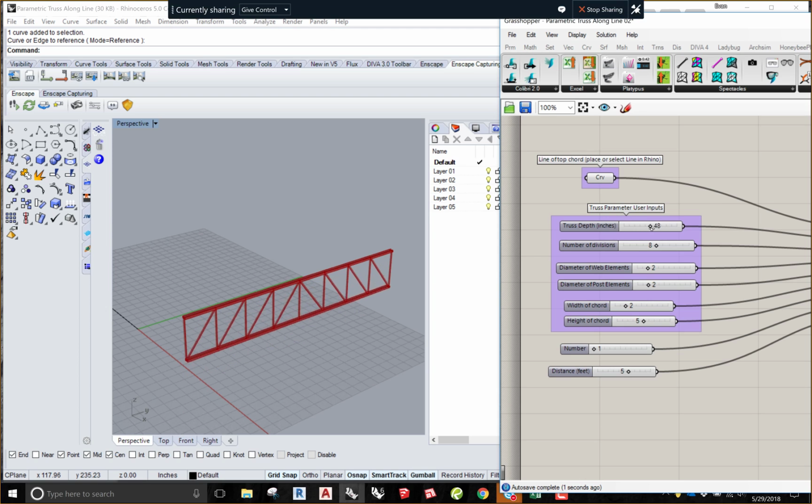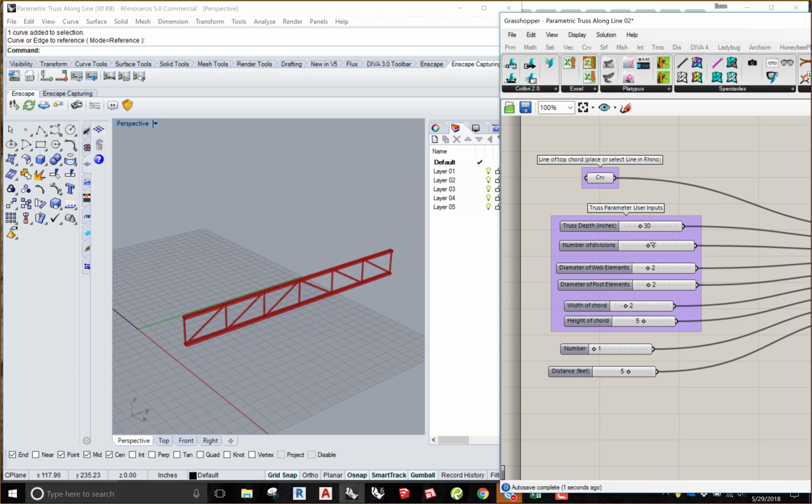And you can see it's all stretchy. And I can go over here and change the number of divisions. And just make it look good, make it look right so it represents a truss, right? I'm not building a real truss. My structural engineer is going to do that in Revit Structural. But this gives me a great way to visualize what these things are looking like.